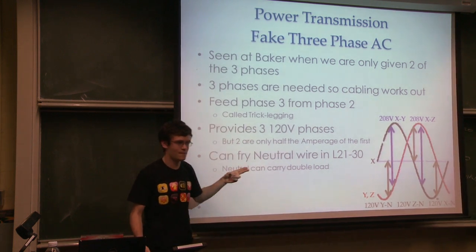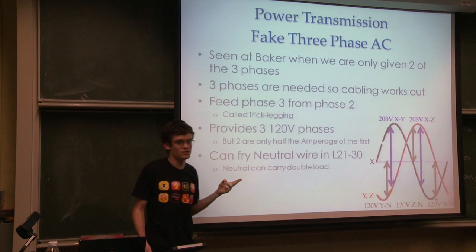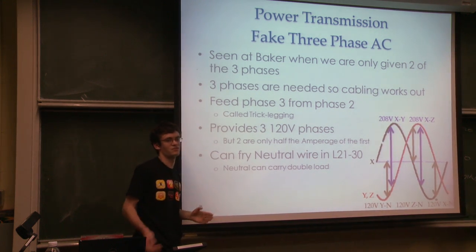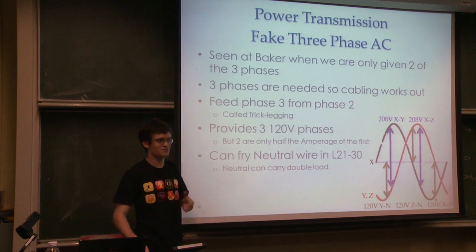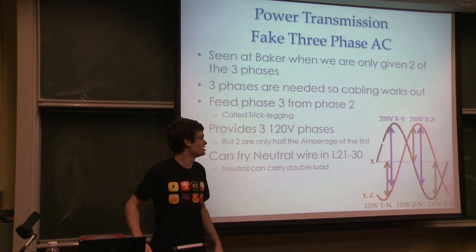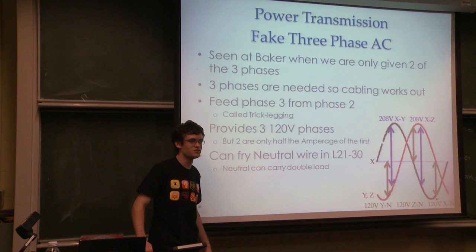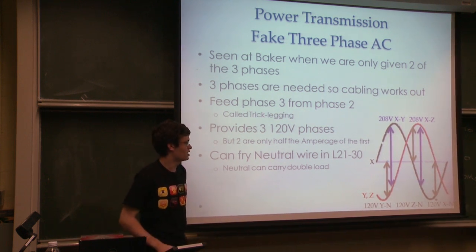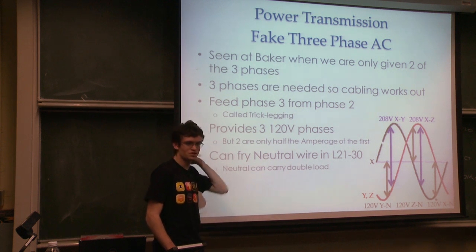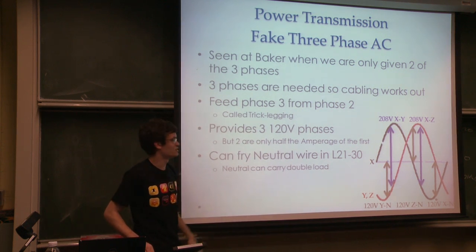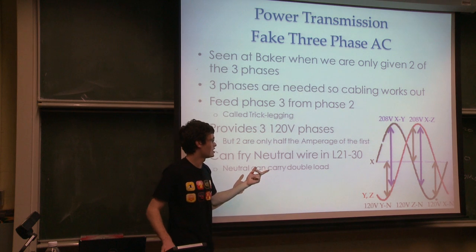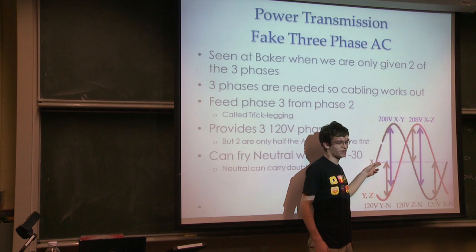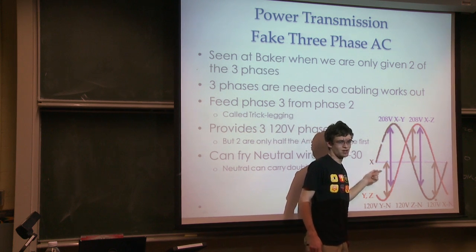This is really only beneficial when you need a bunch of 120 volt lines and you're just using the gear that provides 3 hot lines and distributes between them. You don't really want to use this when you need the 208 volts on all 3 phases, because that puts a lot more work on the ME to figure out which one is which and making sure that the balance is better. Because there are 2 hots, you lose the capability of having all 3 phases balanced and having almost 0 load on the neutral line.